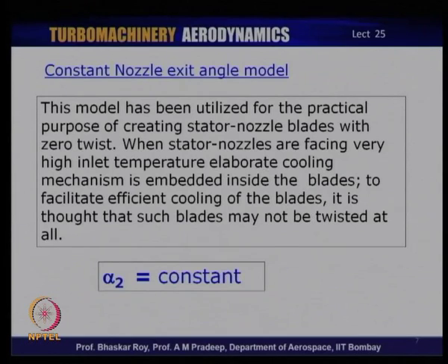So, the turbine blade designers very quickly decided to adopt this particular design philosophy to create an untwisted stator blade, so that the cooling can be efficient, because for the last 50 years the advancement of turbine design has been more through the cooling technique and by increasing the turbine entry temperature to get more work out of the turbine, rather than creating more and more complex aerodynamic shapes.